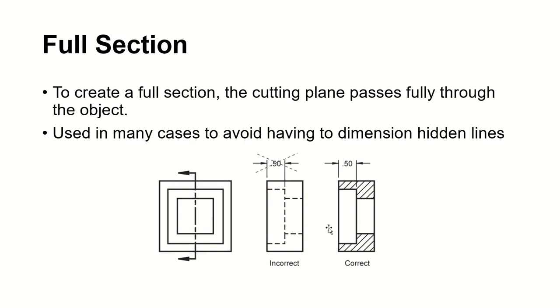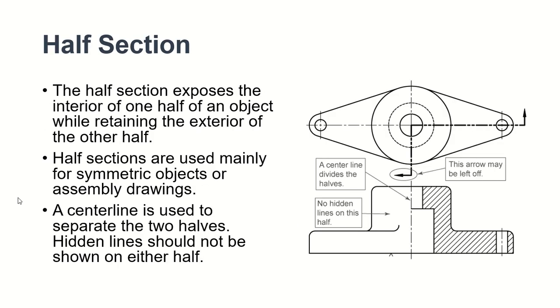Your edges are, of course, invisible lines right there. This is your cut line. We will keep this. After you cut it and toss it out, look inside. It's kind of like a right side view. Open it, and you're going to get this. Section it, meaning put the section lines, showing the cut material. This is hollow. Alright, you'll have a section.